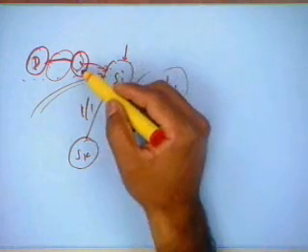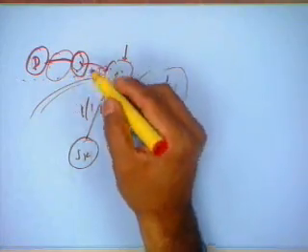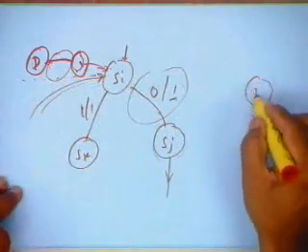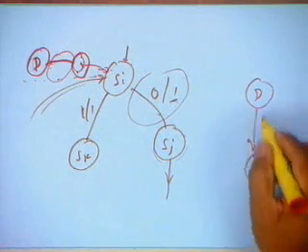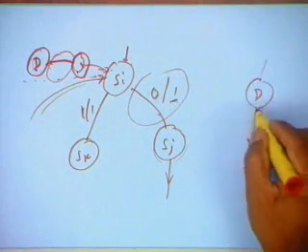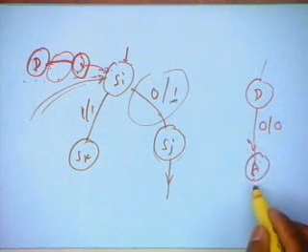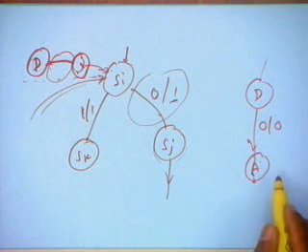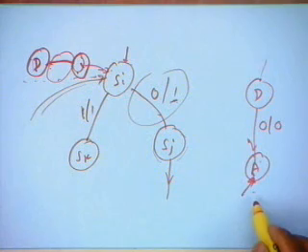So once I apply the distinguishing sequence, I will know what is the initial state I started with. Let us say this was a transition which was going from D to some state, let us say A. These are the transitions. So, I reach D through a homing sequence, apply the inputs required to perform the transition, and then once I reach there, I apply the distinguishing sequence and verify that I started from state A.